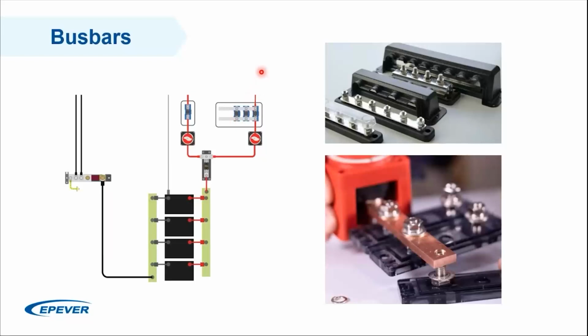In my case, for simplicity, I have one inverter, and I've used this terminal of the busbar, which also has a fuse, to connect the batteries to my inverter. So you can buy a pre-made busbar, or you can create your own. With a piece of cut and drilled copper bar and a few fuse holders, you can create a DC distribution system.